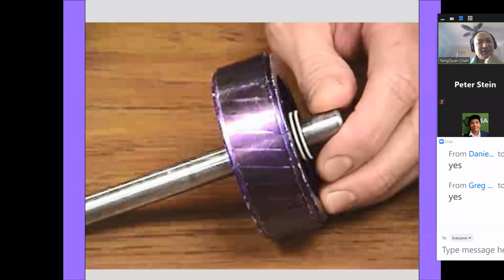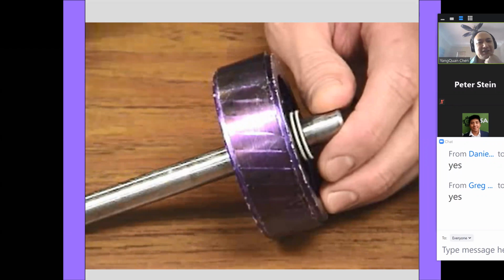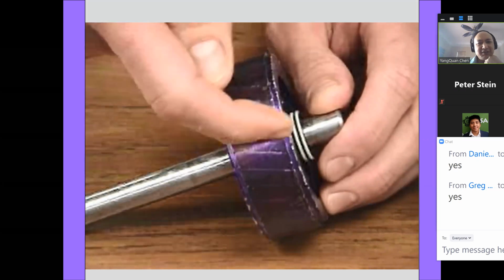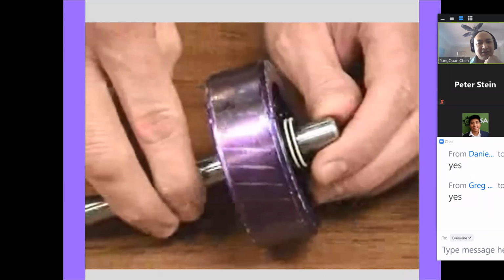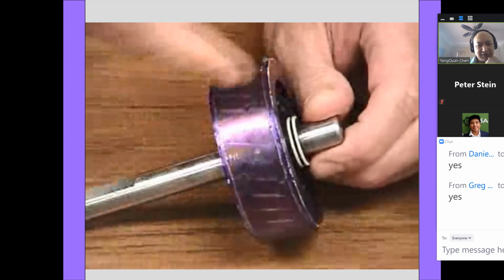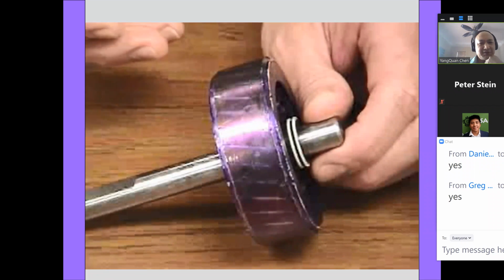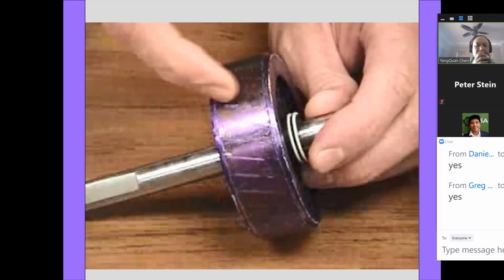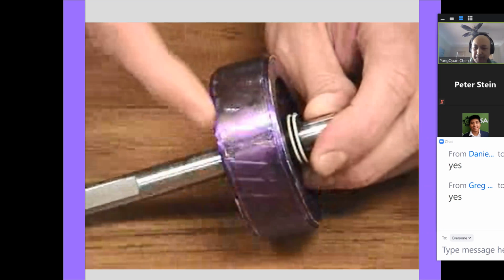The rotor in an induction motor is the classic squirrel cage design. The squirrel cage is embedded into the core, which makes it difficult to see the actual squirrel cage. Taking a closer look, these lines going across are the individual bars of the squirrel cage. The lines are on a slant here, where the bars are angled in order to develop startup torque in this particular single-phase motor. The actual rotor bars are shorted out on both ends by shorting rings.